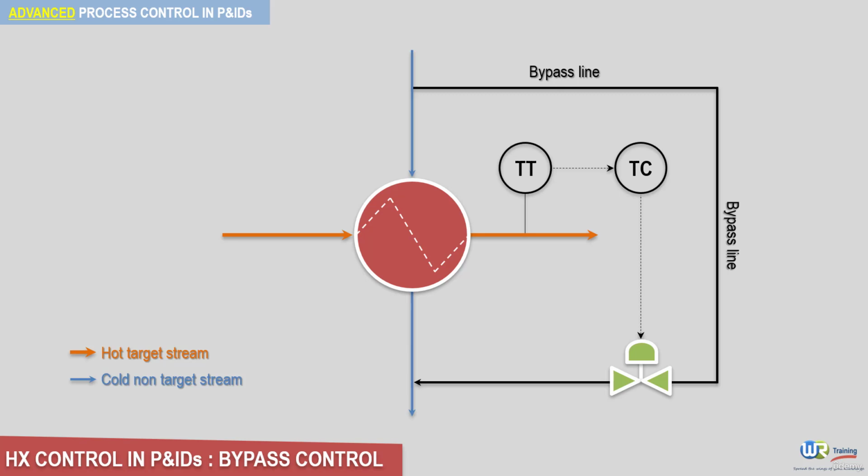This is a better arrangement when the cold stream is a process stream and has another responsibility downstream of this heat exchanger. However, the temperature of the cold stream is still changing, and if it is not tolerable, we cannot do anything for it in this heat exchanger. When the fluctuation in temperature may be too great for the equipment downstream, we can solve this by putting another heat exchanger in series with this one to control the temperature for the downstream equipment. The second heat exchanger must be a utility heat exchanger.